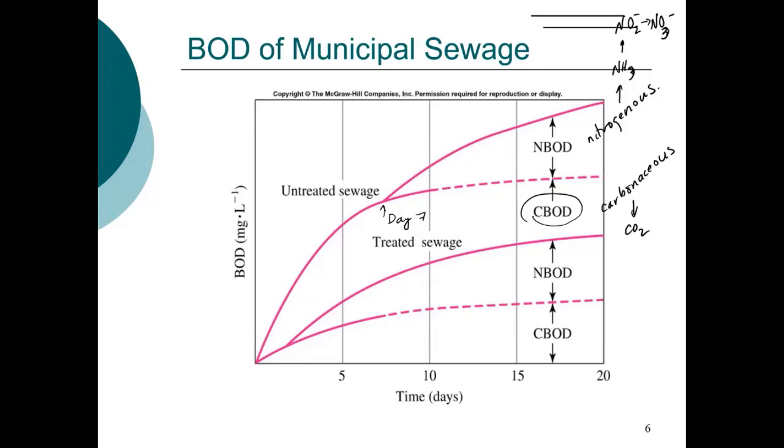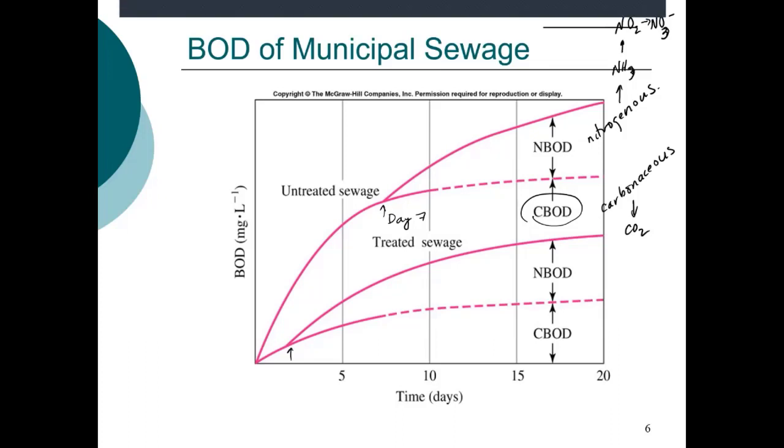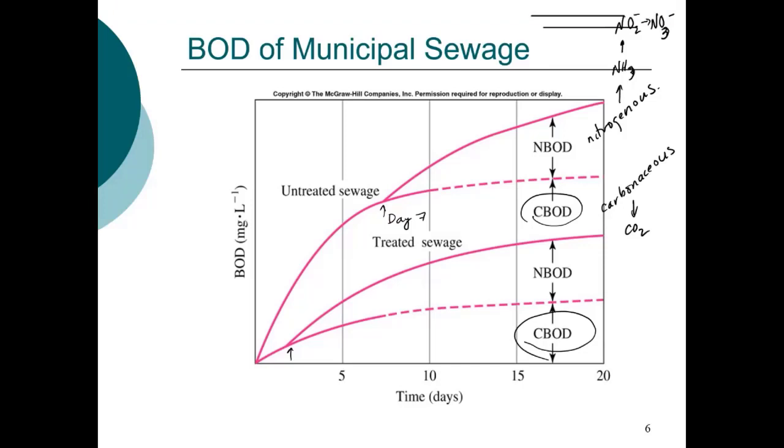The treated sewage, notice after about maybe a day and a half, you start degrading that nitrogenous material. And that's because most of what we focused on in the treatment is that carbonaceous material. So in oxidizing that carbonaceous material so that it doesn't exert an oxygen demand, it isn't consuming oxygen in the receiving body of water.